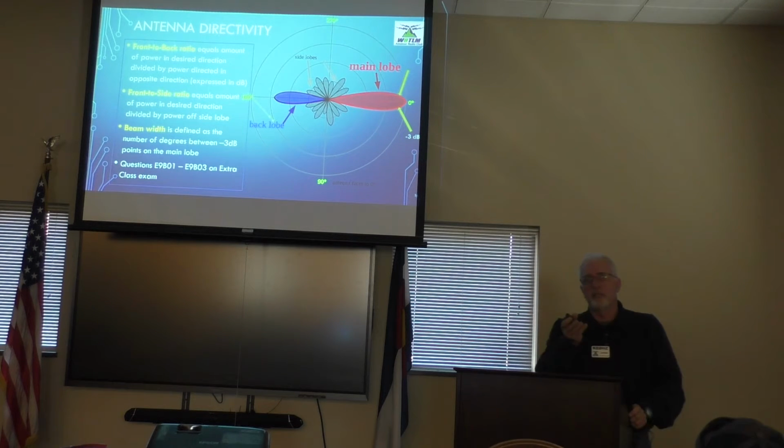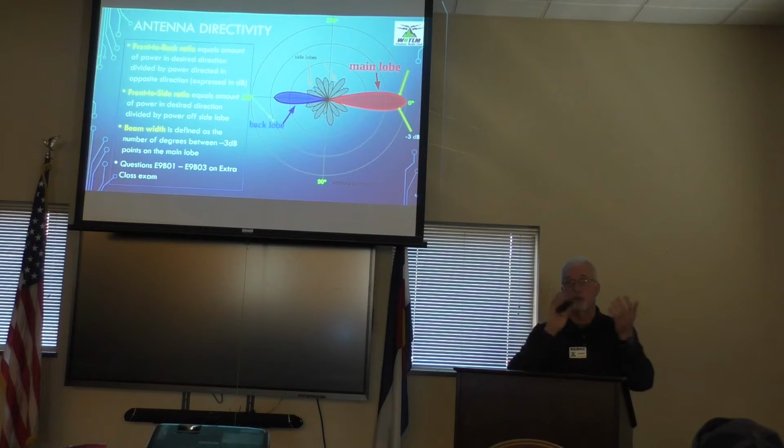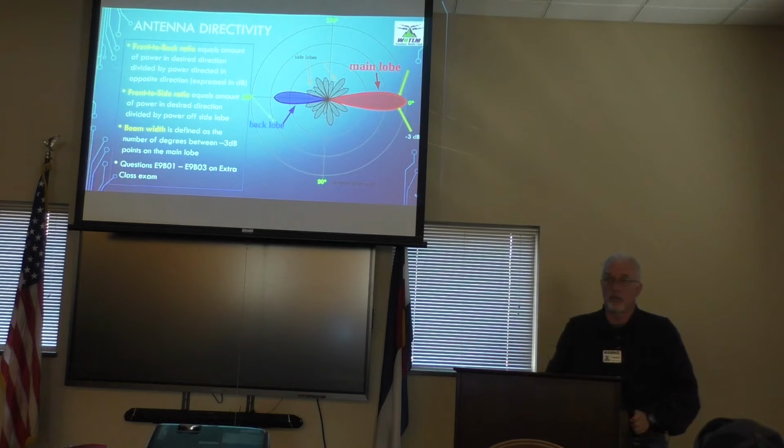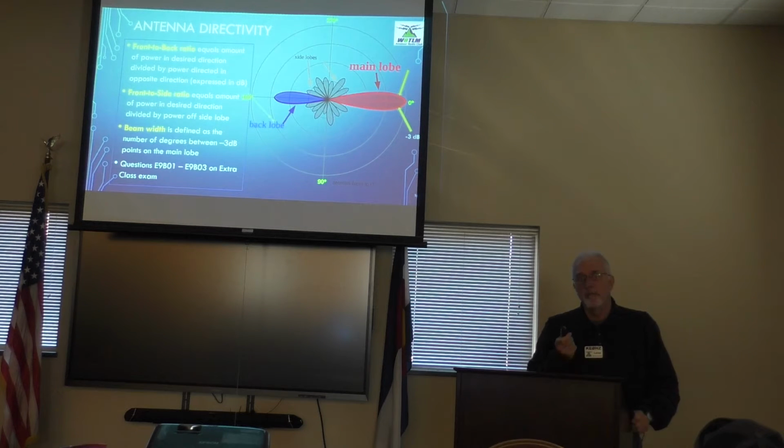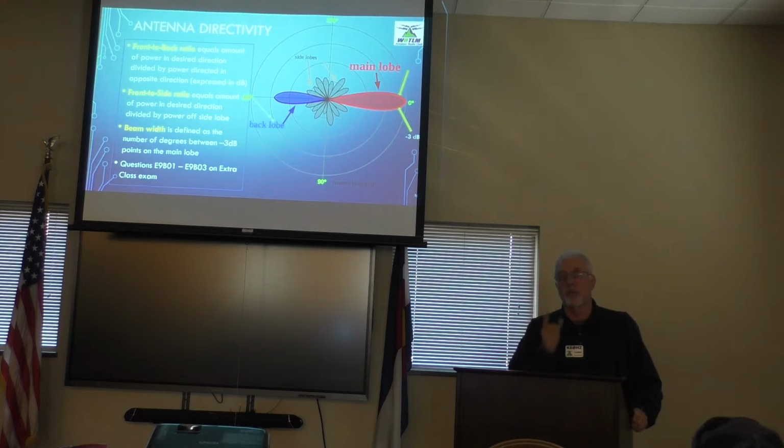So they're really done the same way, and the reason you would choose one over the other frequently depends on how high can you get it and the space involved. Because the quad antenna will have a smaller turning radius because you've got elements that are not stretched out horizontally. But in terms of being more efficient, without being able to measure the field strength of that antenna around, it's kind of hard to answer the question. But it would be more effective.